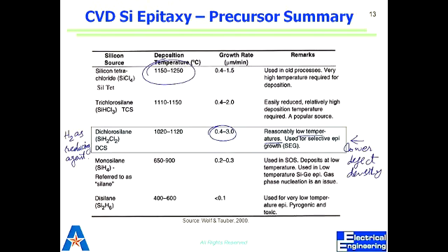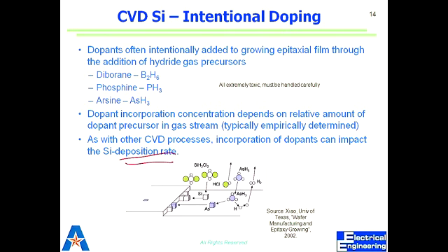It's not only that, we have to do doping also while we are growing. So there, again, diborane, phosphine, arsine. We looked at it for the doping of polysilicon. So we can use these to get the film already doped once we get it, right?